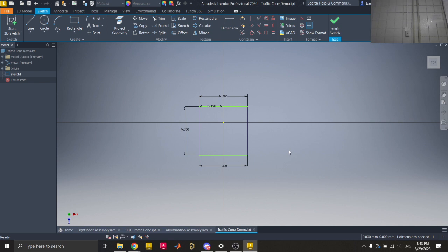So you already have dimensions there, so it shouldn't move. But if I wanted to move it, then you'll need to delete the dimensions that are locking it. So if you delete those middle ones, can I delete that? Yeah, you can just select it and use the delete button. Here, hit the X really quick. Let's escape out and just click on it, and then hit delete.